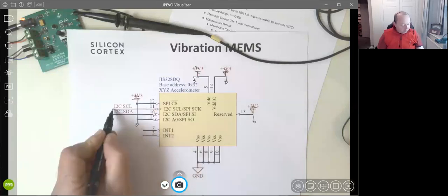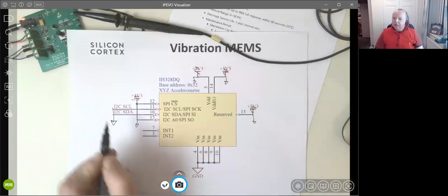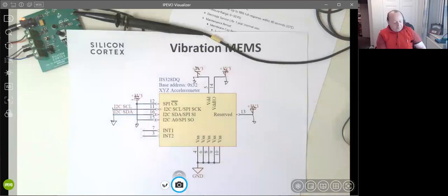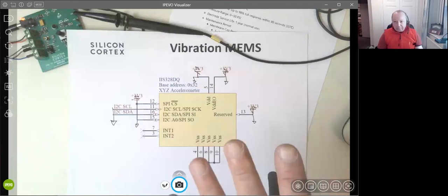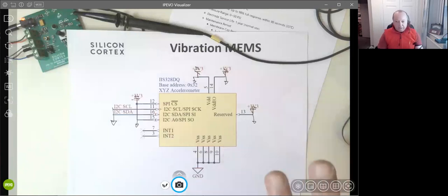So it's called Stiction. MEMS devices do suffer with this problem. And so in terms of solving it, I've had to put into code in the ARM core, if it spots that the accelerometer's not recording anything, then it knows it just needs to depower it and restart the device. So that's a challenge. But yeah, that's my challenge at the moment, vibration.